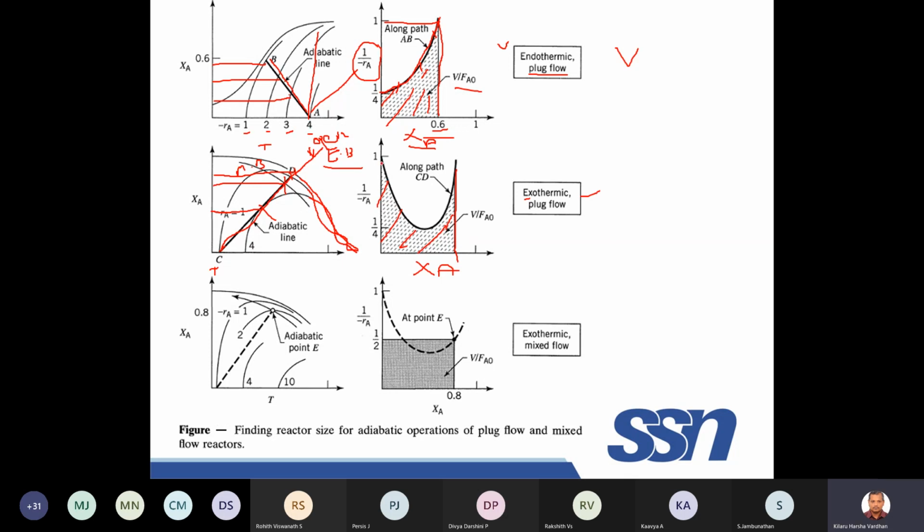So this entire thing is almost like an autocatalytic reactor. We know that for an autocatalyzed reactor, instead of one PFR, you put a CSTR till this particular point, your area will be minimum, and then go for PFR, which minimizes the volume instead of one PFR, right?